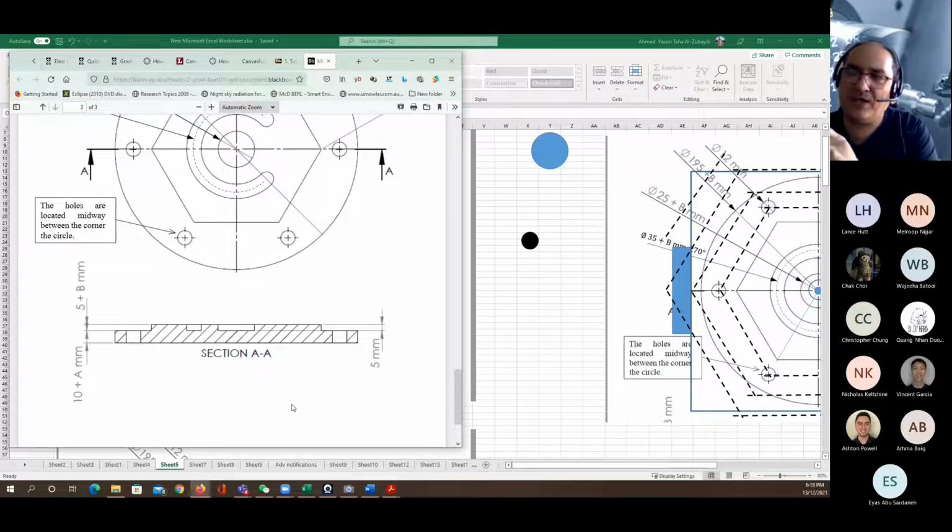So it's always recommended, if you have something about 5 millimeters, to cut it as 3.5 millimeter first as rough cutting, and 1.5 millimeter later as finish cutting, because 1.5 millimeter is the maximum depth of cut I can use for the finish cutting. If it's lower, it's going to be better. So if it was me and I needed to cut 5 millimeters, I would do it as 2, 2, and 1: 2 times 2 rough cutting, and 1 in finish cutting.